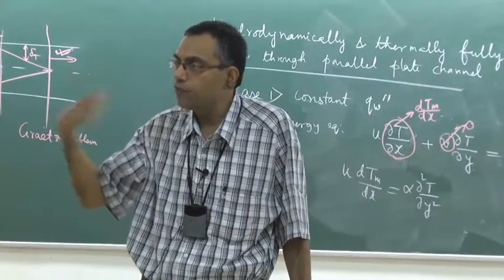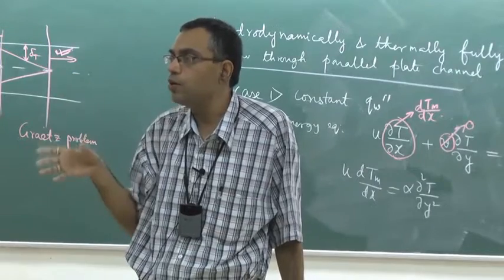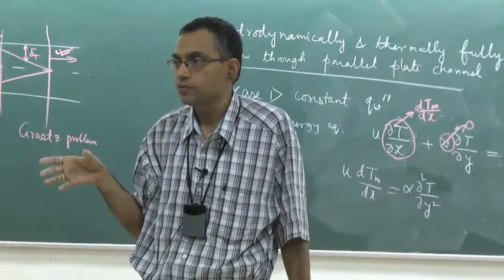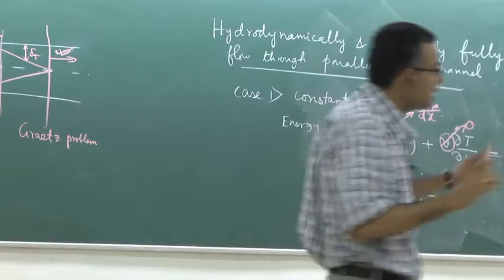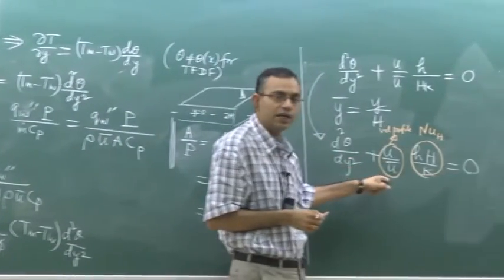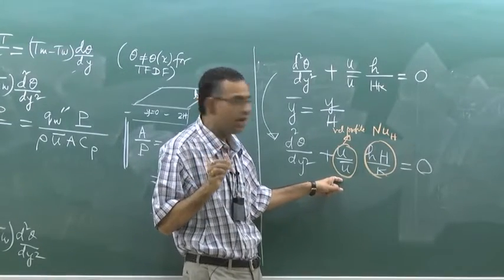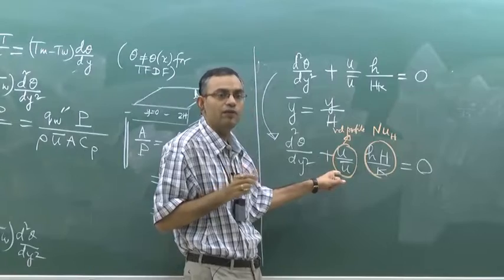If you have a plug flow or slug flow, that means a uniform velocity profile, then what is u by u average? 1, right. So that is a very special case, with very simple algebra to deal with. I am not working it out here, but please take it as homework and complete it by yourself: consider a plug flow with u by u average equal to 1.